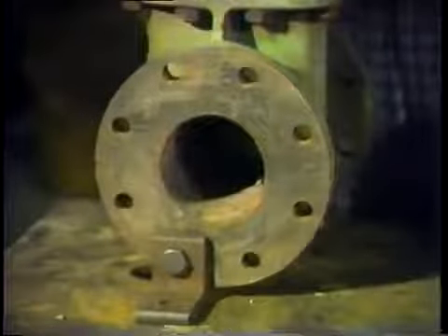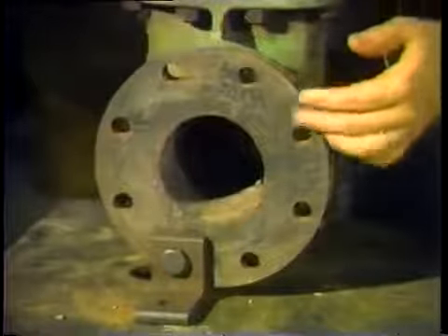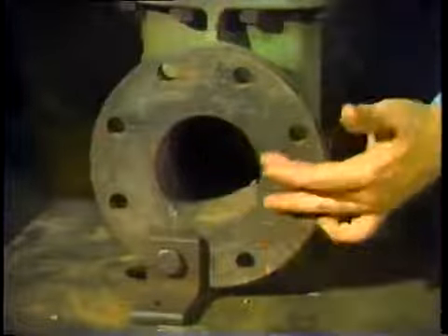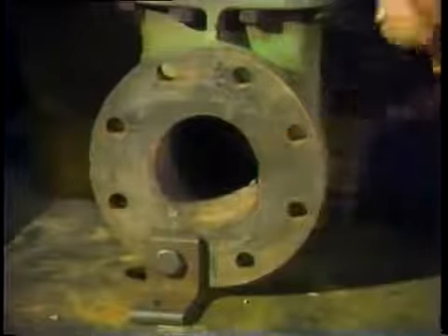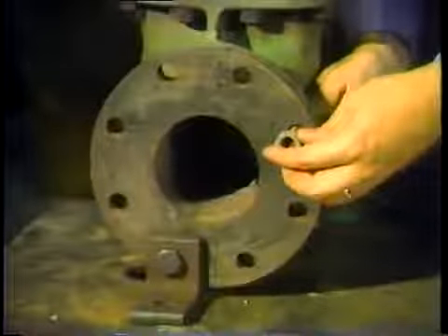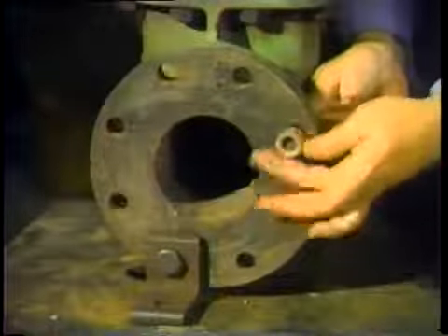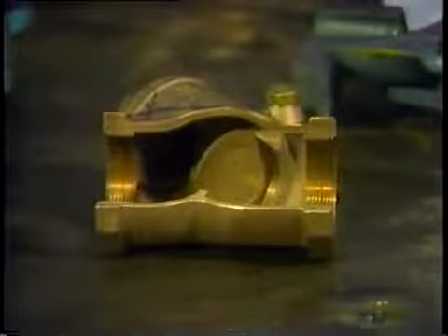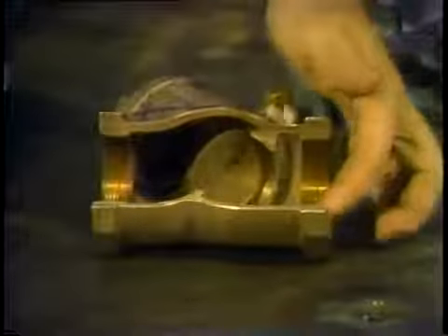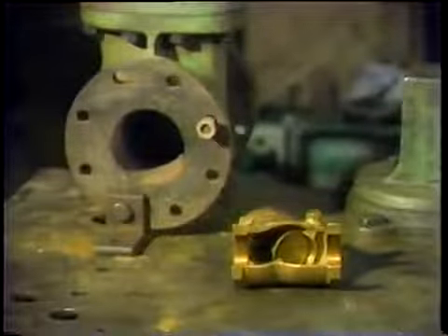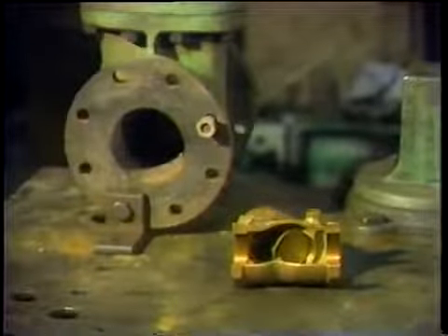The flange is another common type of connection. In this case, the valve is bolted in place, and the inlet and outlet stubs of the valve are flanged like this to allow for bolting with system piping flanges. A common method of attaching a valve to a low-pressure system is by threading. Threaded inlet and outlet stubs look like this. These are the ways a valve can be connected to system components.